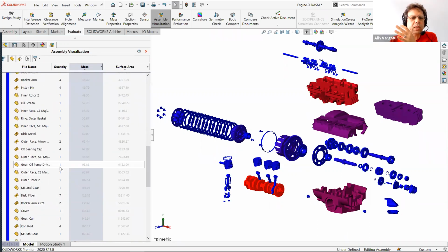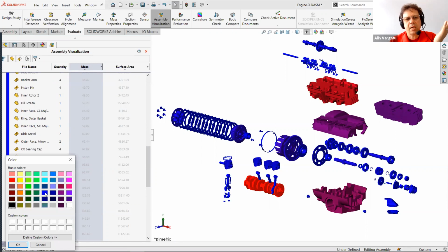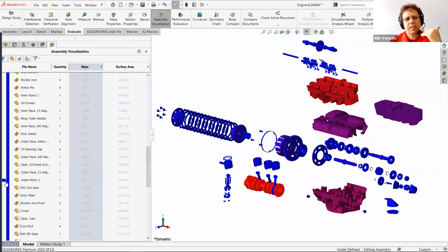Well, let's find out where 100 is. It's somewhere here, and you simply click on the left of the color bar. Notice there is no button there, but the moment I move my mouse there, the cursor changes to a hand and it says add slider. So let me click there and pick the same color that I had before, since I don't want a change in color between the two of them. You can see a blue is added right here, and let me move it just above the 100 mark.